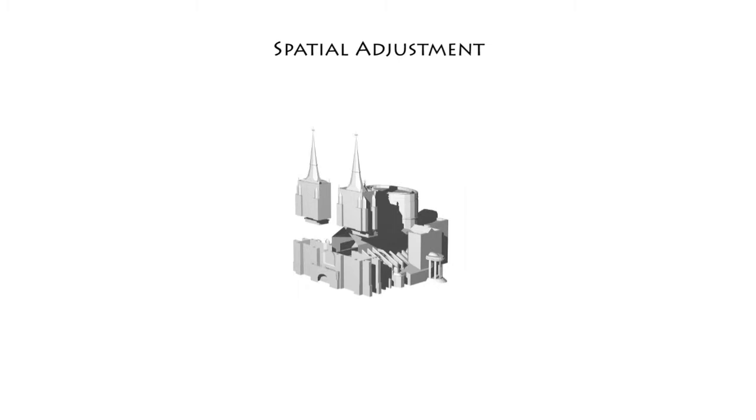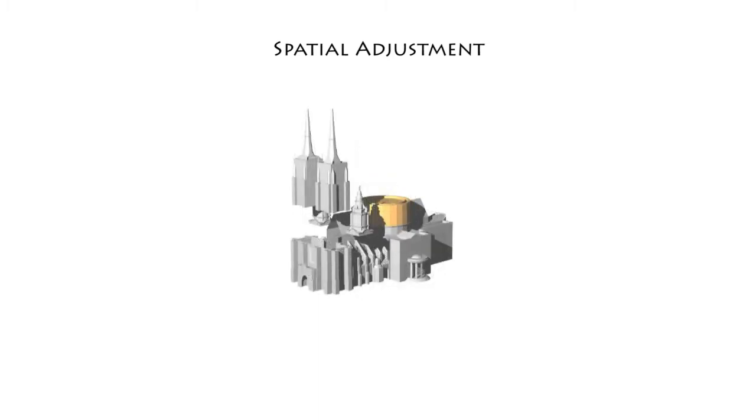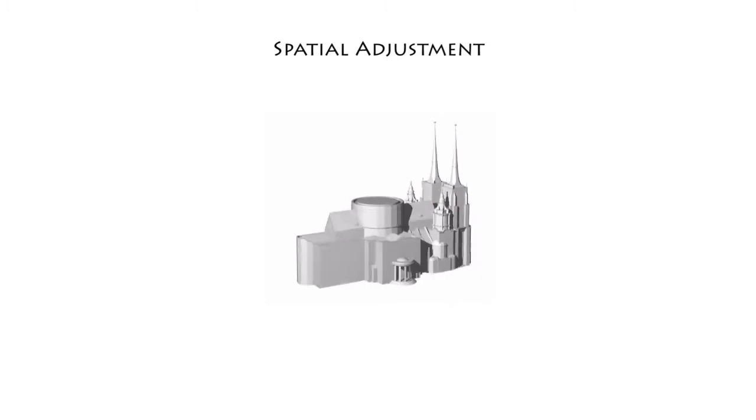In practice, we use spatial adjustment to remove artifacts in the output model. For example, normalization of a cylindrical shape can result in distortions. This can be removed using local resizing. Some parts may float in the air, and we shift them down to the nearest neighbors. Any remaining part which is not fully supported has its base extruded to the ground. Here is the final output.